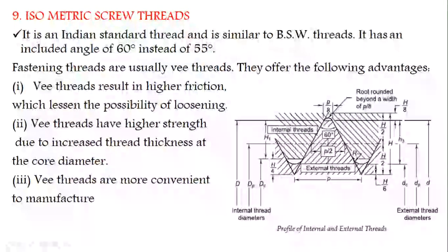The coarse threads are easier to cut than the fine threads. The coarse threads are less likely to strip during tightening. Coarse threads have more even stress distribution.